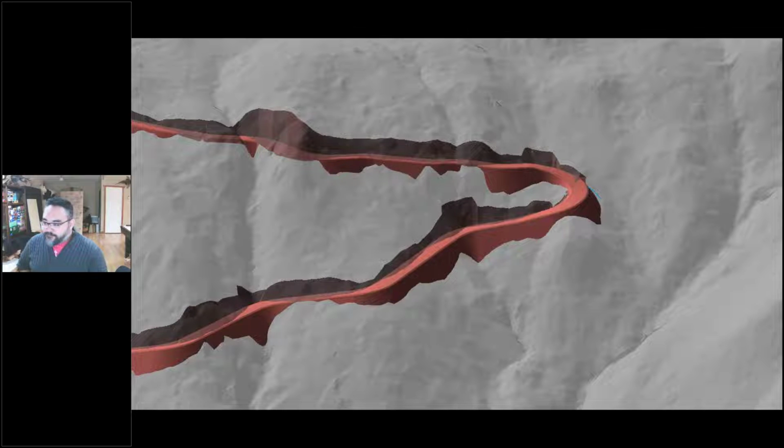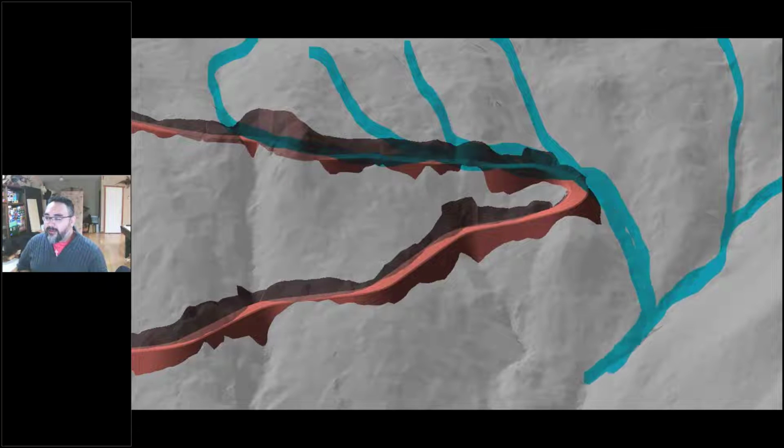Now when it rains, the water comes down the hillside and it hits our road. So that's not just in the drainage courses, like I said, that's that surface and subsurface flow all along that cut slope. And so in this case, as our road climbs up, we're intercepting all of that drainage. And if it's flowing down the road or in the ditch, it'll flow to a point until it can get off. Well, in this case, and like I said, if you look back at the history of landslides in coastal British Columbia anyways, this is a super common reason for landslides. That water flows off the end of the switchback.